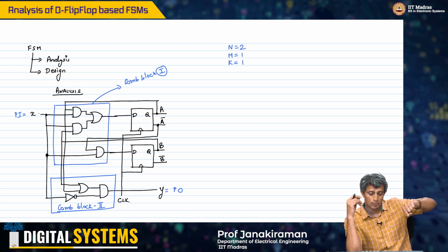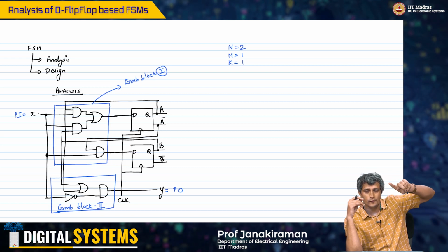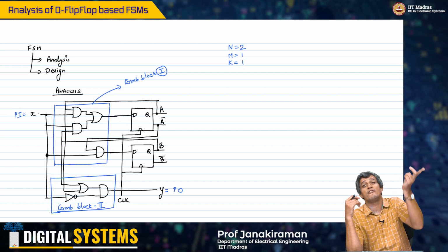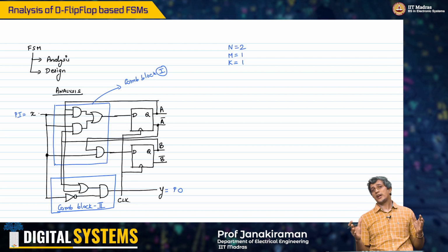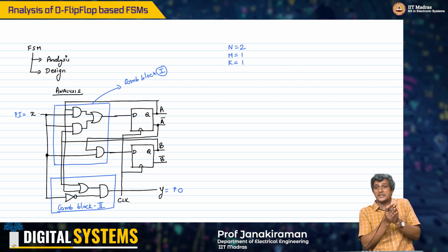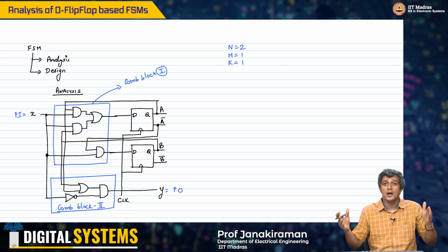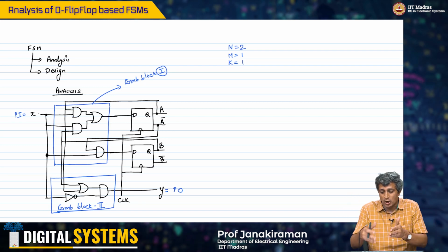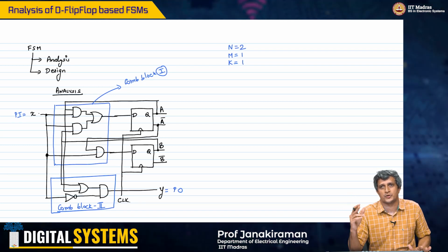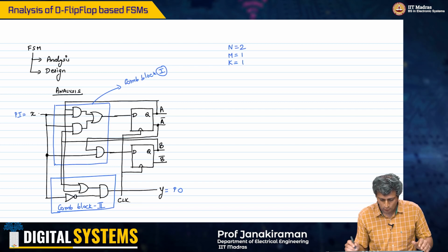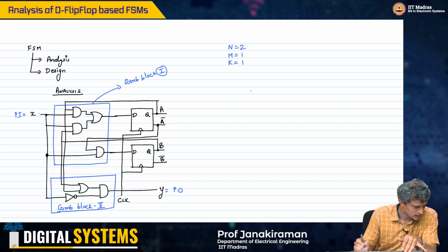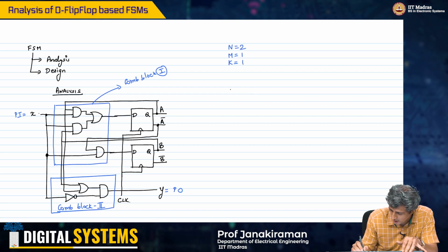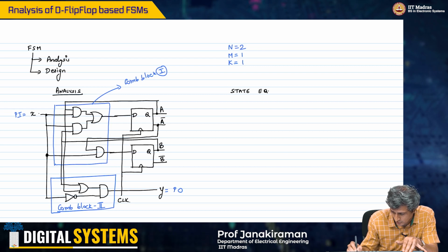We are going to worry about if the flip-flop was in 0 0 state, then where can it go next? Okay, so based on this we are worried about all possible state transitions and not just the number of possible outputs of the flops here. Okay, so therefore what we first do is we define what is known as the state equations. Okay, so what are my state equations?